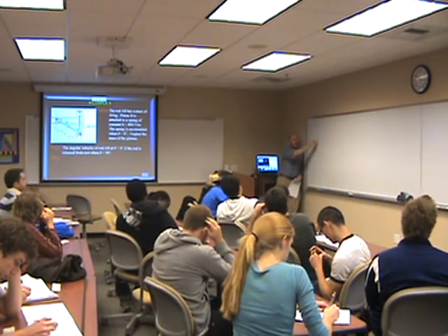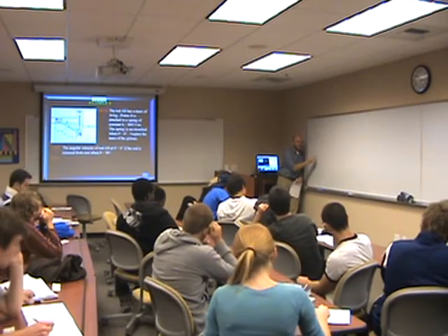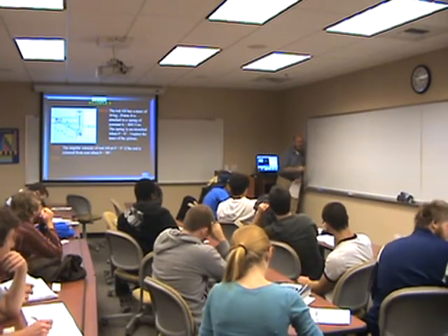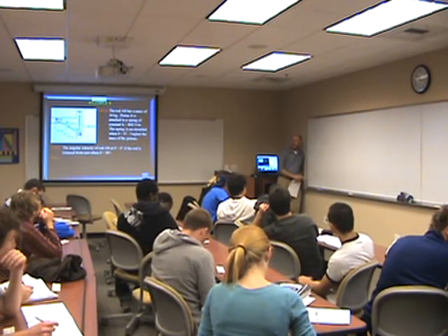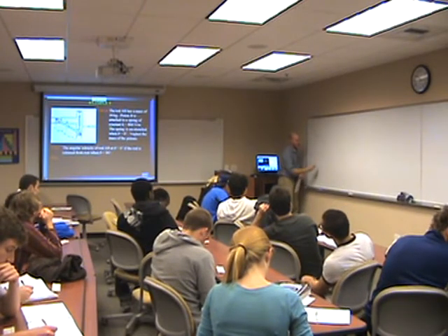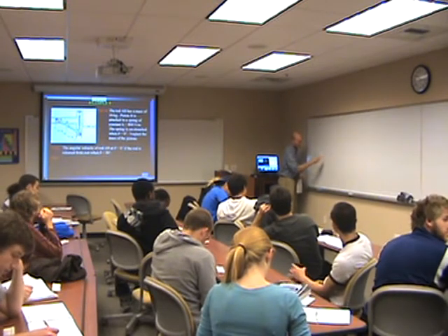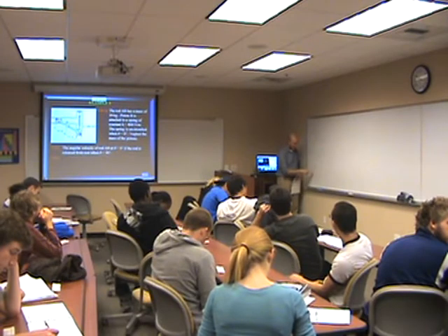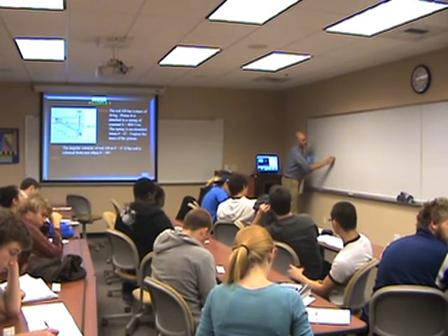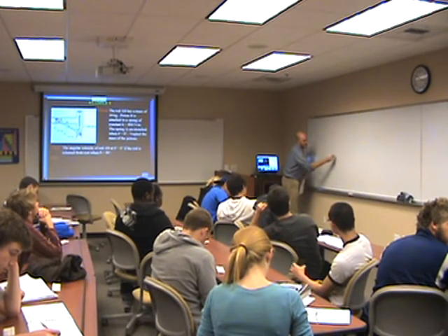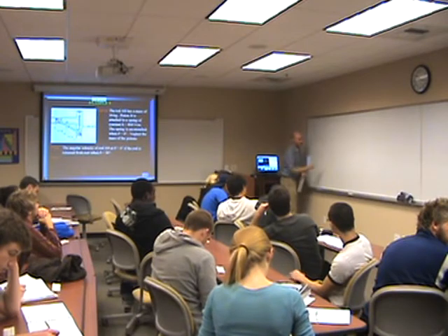This is the V of the CG, and this is I about G. Therefore, our kinetic energy, plugging everything back in, is 1/2 mass times 0.2 meters times omega, squared. What's our mass? 10 kg.